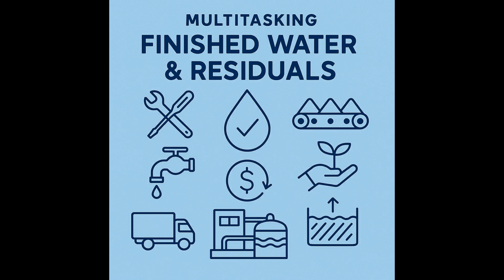4. Field execution and maintenance. Have solid QA/QC procedures for your hauling and application contractor. Actively manage potential odors. Have contingency plans. What's your backup disposal option if fields are too wet for weeks? Do you have critical spare parts for your dewatering and loading equipment? That's a comprehensive list. So, weighing it all up, pros and cons.